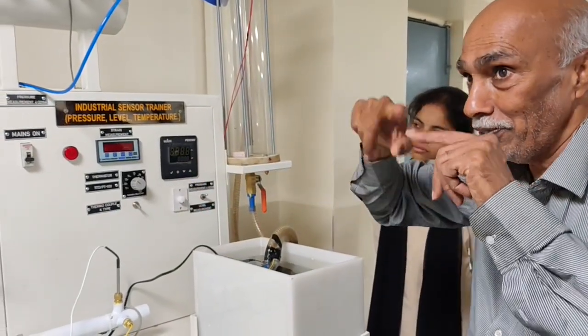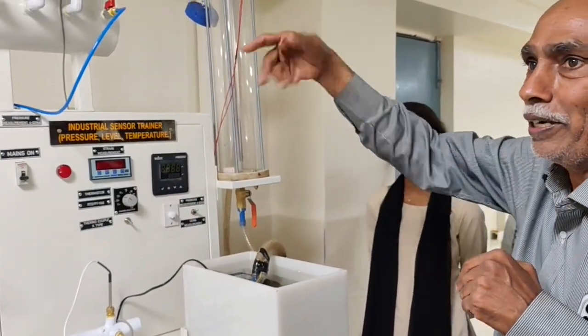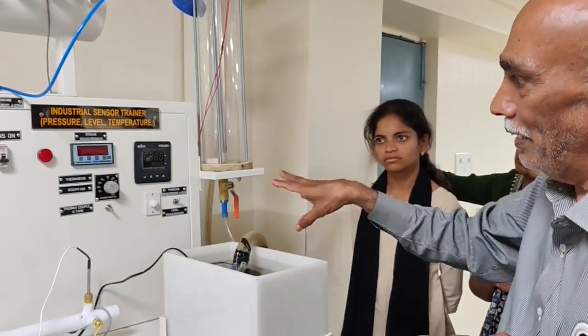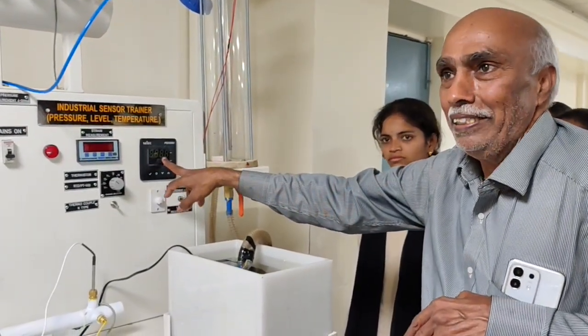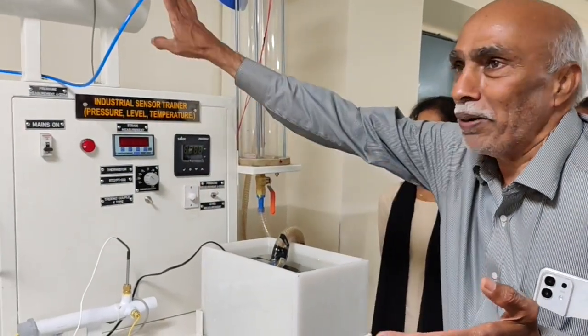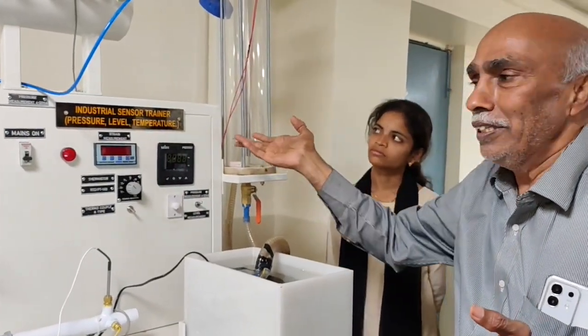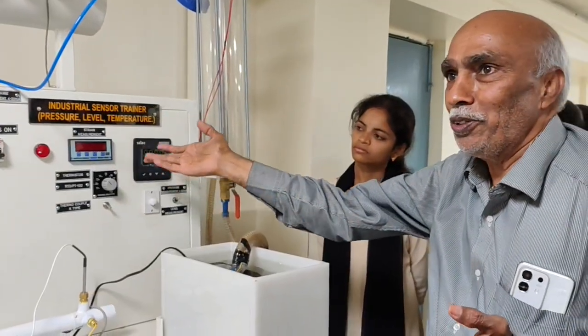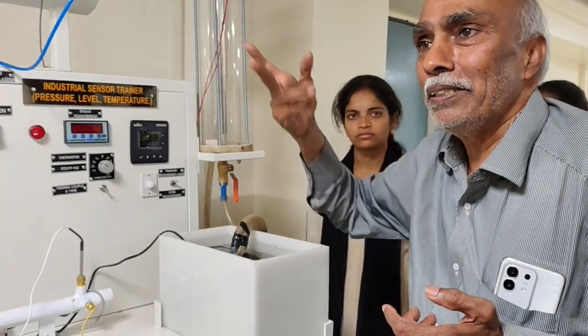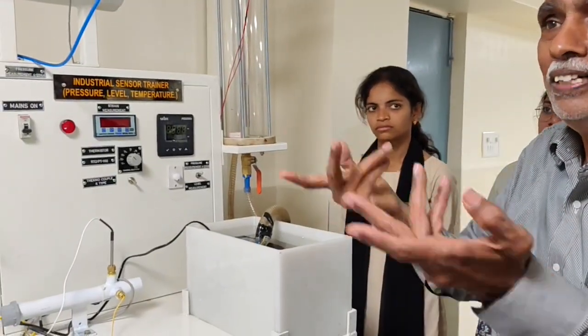Actually, it is coming here in millivolts only. But you are reading it because of the scaling, like 2 liters, 3 liters, as you read at the petrol bunk, no? It will be like that. Scaling will be done in the meter. It is called scaling, as per your convenience. Both are common. Both will produce the same. Sir, both are producing the same. How you are reading 2 here, you can ask the question. Here it is in millimeter, there it is in kg. It is your scaling, as you find convenient.